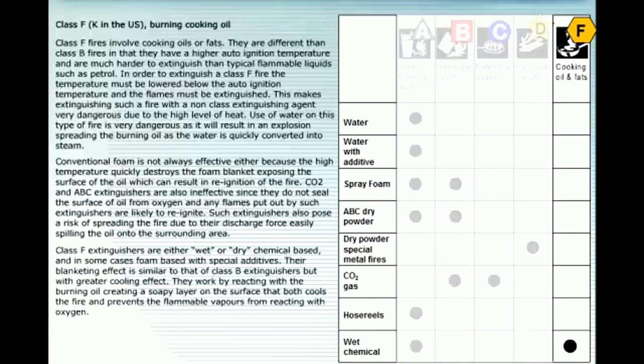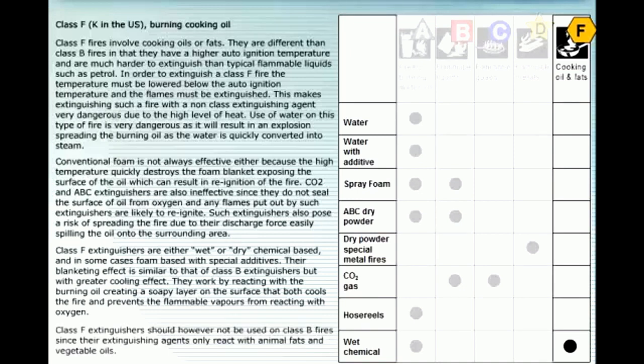Water is normally the most suitable extinguisher to fight Class A fires. Water extinguishes the fire by cooling it below the ignition point. That means it removes the heat side in the fire triangle. Water is a very important extinguishing agent on board. It is cheap and easily available in large quantities.